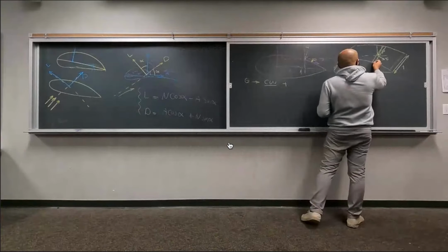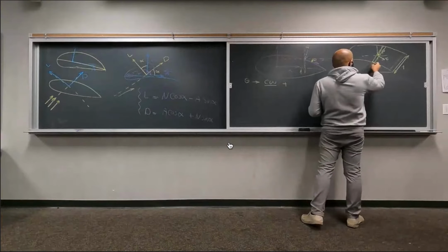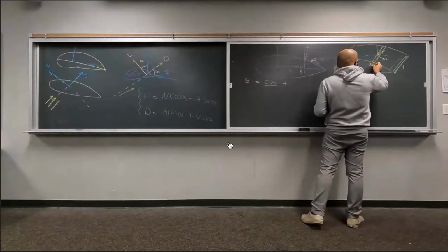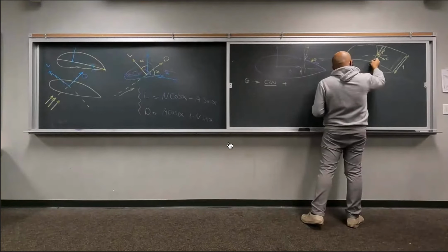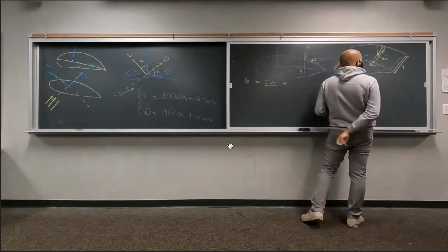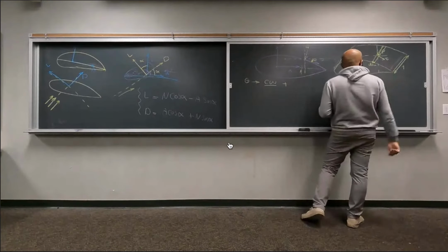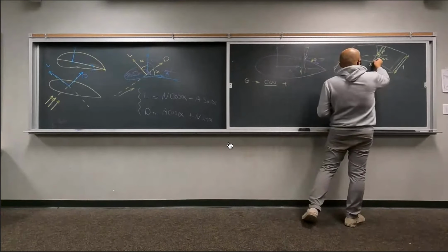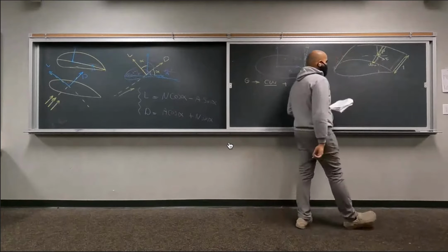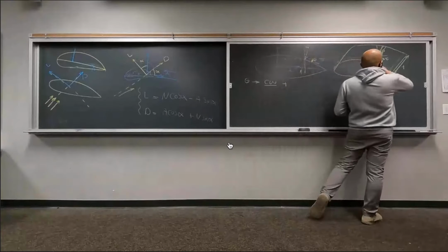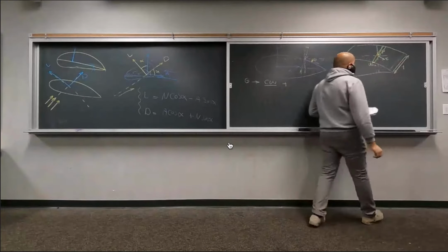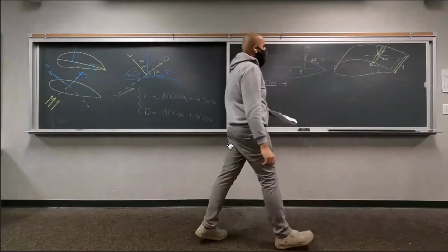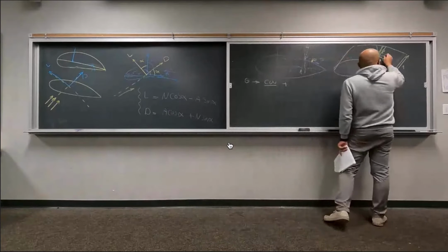And we also are going to assume that the pressure distribution over this small band, we are going to call it ds, dsu, because it's on the upper surface of the wing, and it's just the length of this small band. So the area of this small band is going to be ds multiplied by 1. And we have the angles.